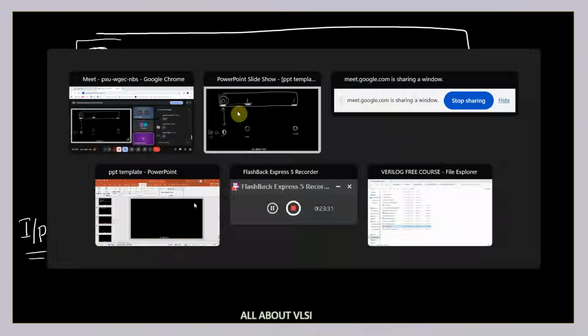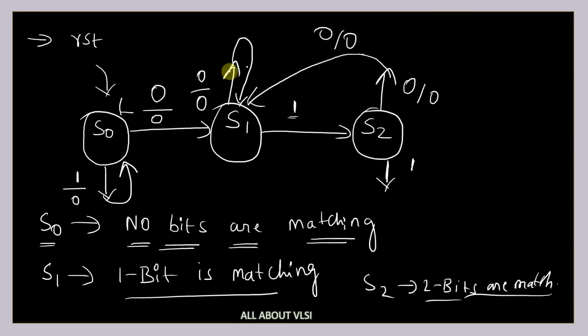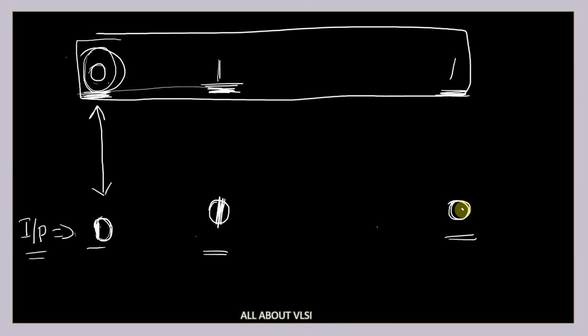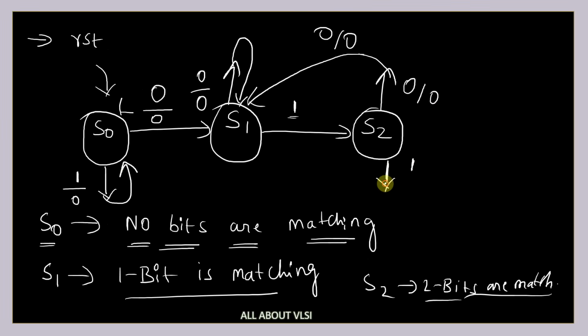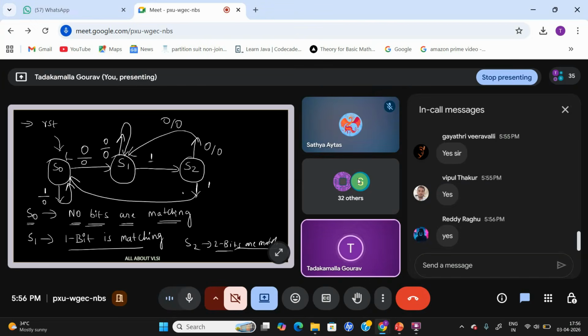Yes. Okay. So I'm going to write down 1 and I've drawn here 1. Now, instead of 0 over here, let's say if I'm going to get 1, then you can see 0 1 1 and 0 1 1. Has the sequence matched or not? Yes, the sequence has been matched, and I simply go to S0 state. There will be something like overlapping and non-overlapping; I will discuss it later. So this FSM, is it clear how to draw it? Any doubts or queries?